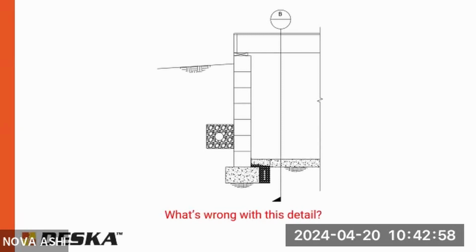No matter how well that foundation wall is sealed or caulked or anything else, at some point the water is going to make its way through. Sealant, like anything else, only lasts so long. And you can't excavate it and reseal it every 5 years, at least not too easily. So drain tiles above the slab. And that's it. I think I'm out of time.